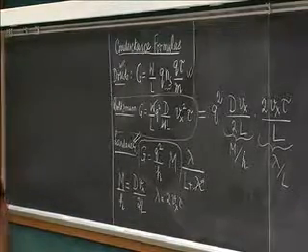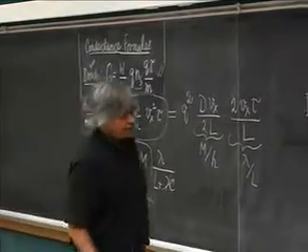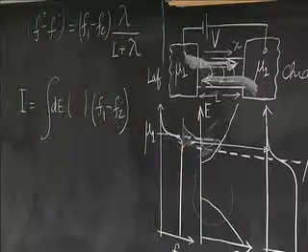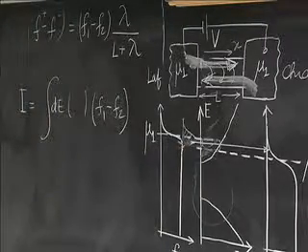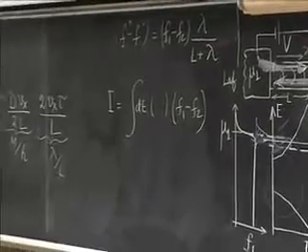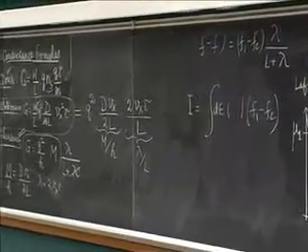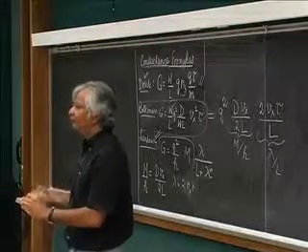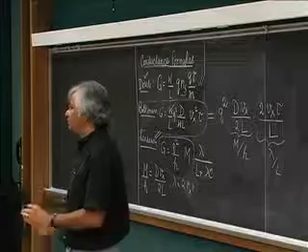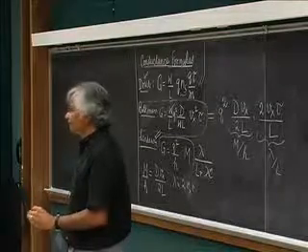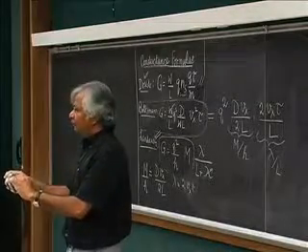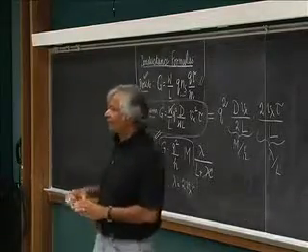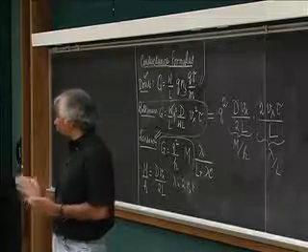But as you know, in conductors, one way to drive current is, of course, put a voltage across it. But another way to drive it is to put a temperature difference. One end is hotter than the other. And one of the very interesting results that I'm sure you all know is that if you put a hot probe and a cold probe, then which way the current flows depends on whether it's N-type semiconductor or P-type semiconductor. That's an experiment, actually. Even I have done this. And it's a very nice, simple result. And yet, trying to understand why the current flows in the opposite direction is not very easy.